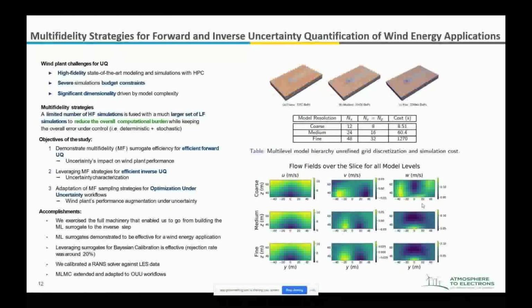We're also applying this method now to some different applications. The past study was a forward study, where you take uncertain input distributions and apply them to output distributions. So we've also done an inverse study just with WIN2C, a RANS model, where we take measurements of the wake. In this case, we used high fidelity measurements from LES, but we'd like to use experimental measurements ultimately, and then find the best samples of input distributions to match those. Again, there's a lot more detail that goes into this, but I'll skip over it. And again, the really novel part of this is we can use different mesh resolutions within it.